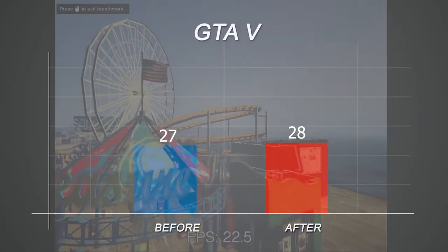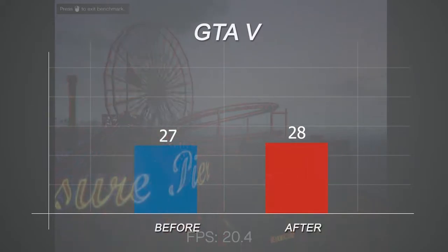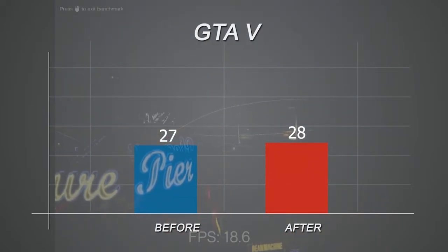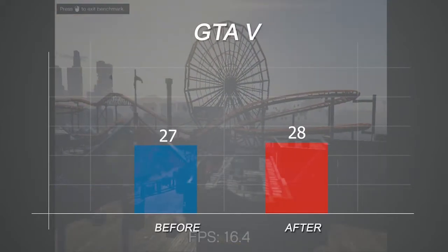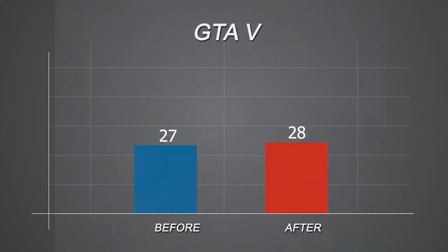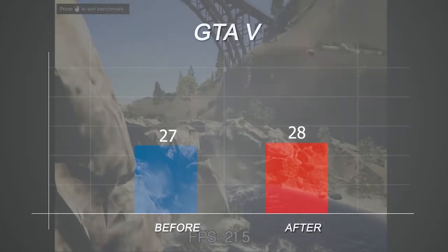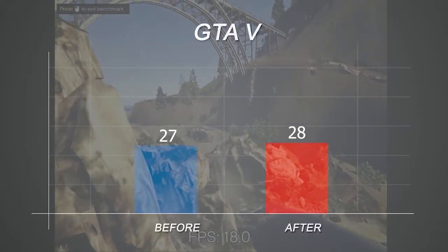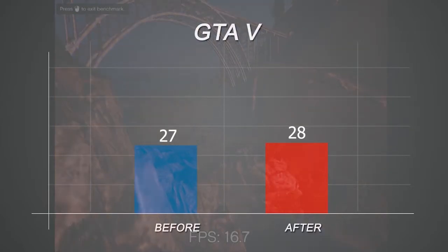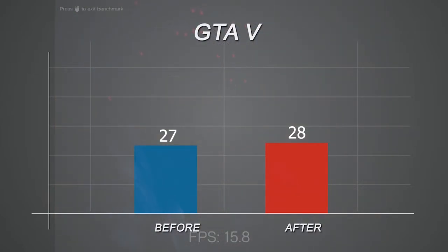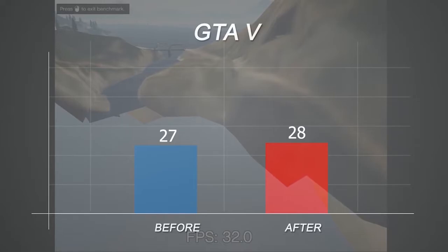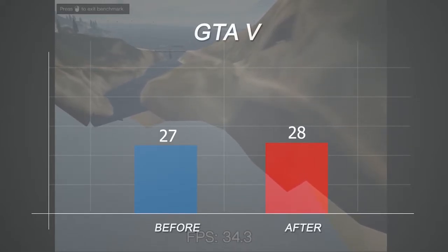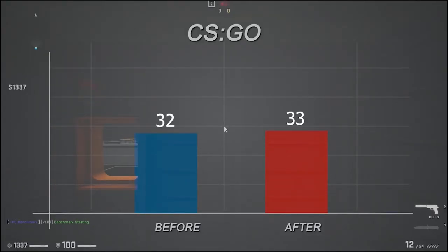In the final scene there was a lot of micro stuttering before, as this scene is especially CPU bound, and if we were power limit throttling, the CPU clocks were going way down, so it just stutters. After we applied our method that improved our CPU clocks, most of the micro stuttering is gone, and the gameplay overall is much smoother.